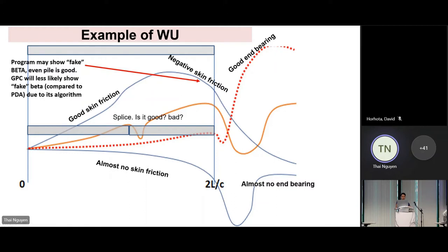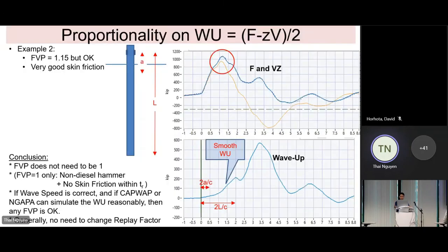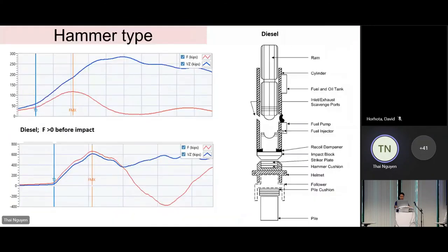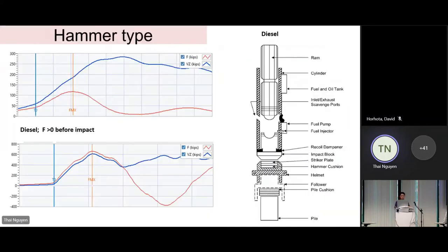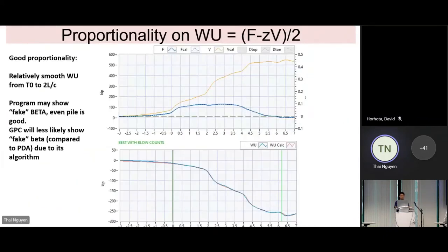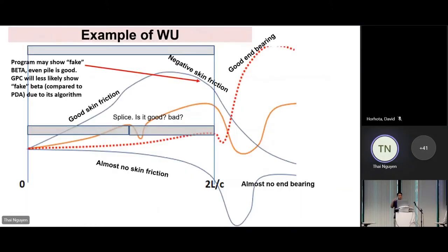transfers to the toe. So for some really large deep pile, if the hammer is too small, one of the examples that I showed earlier, the centrifuge pile. That pile, the force did not transfer much to the toe. That's why you don't see. Let's go back there. Let's go back to this centrifuge pile. Oh, I'm sorry, not in the slide. I presented live. That one, the force did not transfer much to the toe, and because of that, the toe is undetectable.